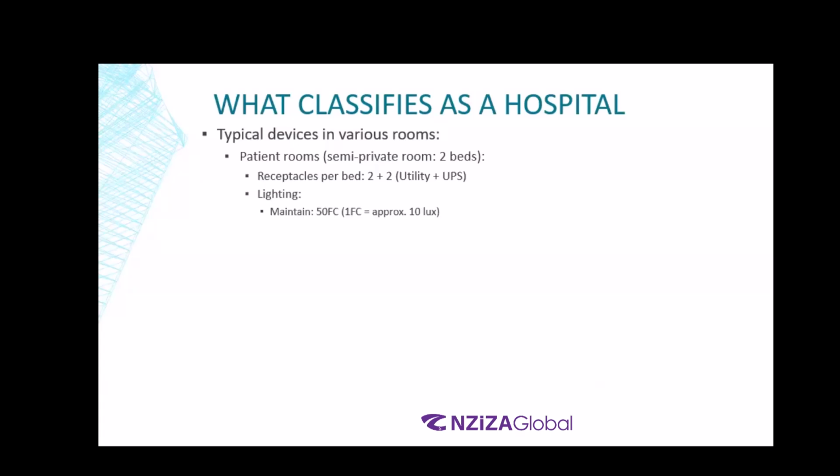Again, lighting stays the same for the general ward as well as the semi-private ward. Basically, we need around 50-foot candles, which is around 500 lux. There will be just one nurse call button.